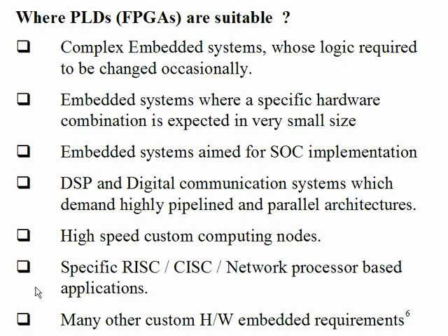But each instruction takes less time. See, you can't judge just by how many assembly lines of coding are coming, isn't it? In a RISC case, each assembly instruction takes only 2 clock cycles or 3. In the CISC case, one assembly instruction may take 18 clock cycles, another may take only 4 clock cycles, or like that. So I explained a few properties. Now let us try to see inside RISC and CISC, and let us also talk about where it is possible to improve the performance.